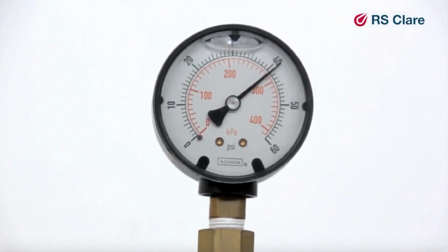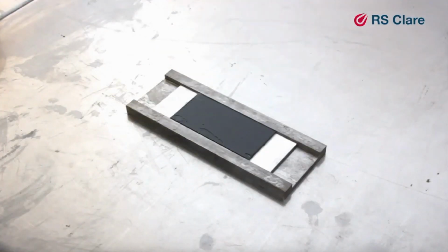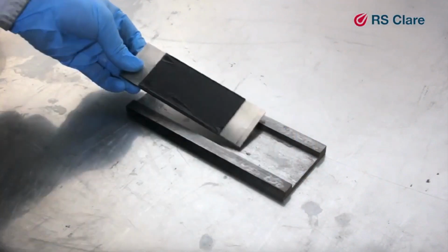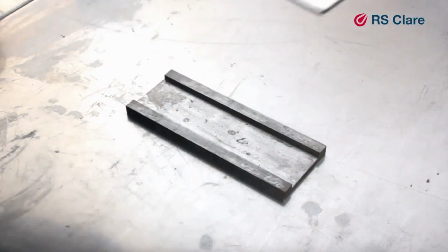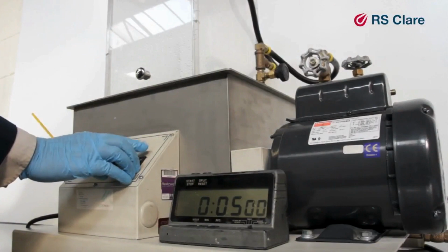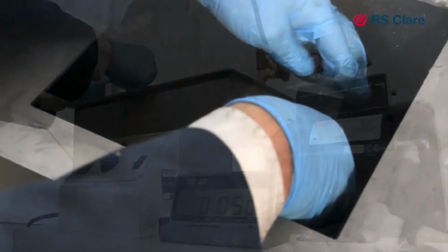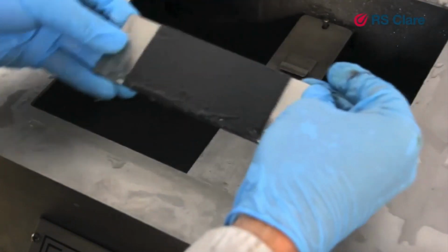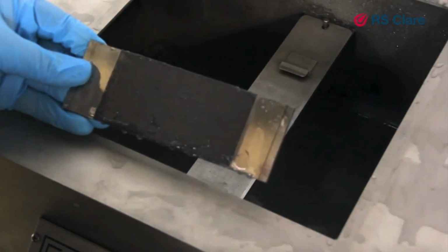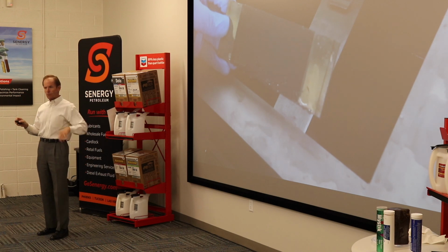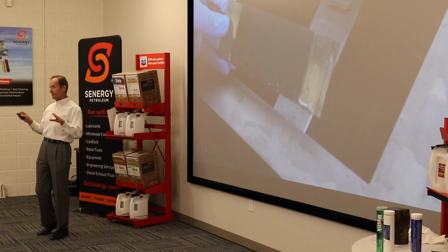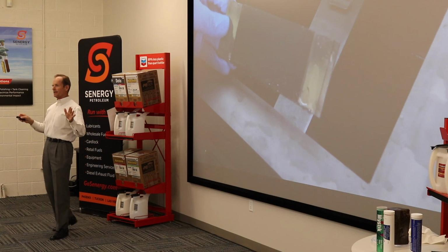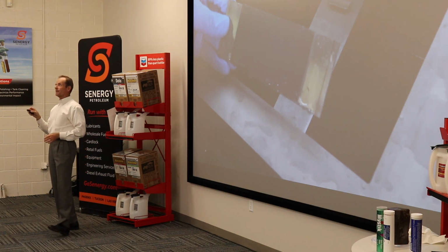These things are reported in percent, how much you lose. You lose 2% or 3% or 5% or 8%. Those are the kinds of numbers you might see. For a given grease run in each of these tests, you would expect it to lose more in this test than it does in the first test. Okay, all right, so those are your water tests. Keep in mind, there are two different common water tests, and don't get them confused or you do yourself a disservice there.